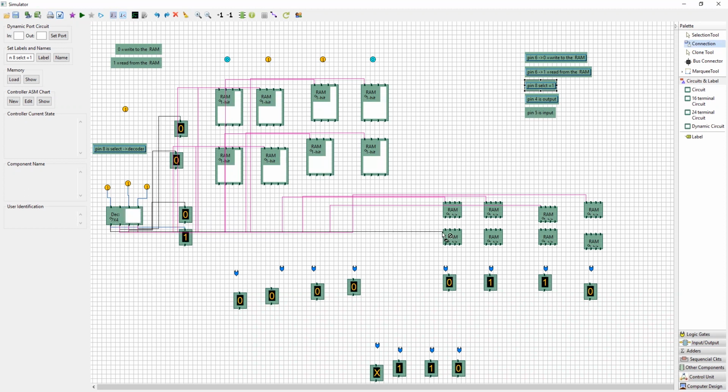So now the last decoder output goes to the last row of the RAM cells. Okay, so I hope everyone is clear on this select concept and how it works. Select is simple: all the RAM cells in a row together I want to select. For that reason, I have given the decoder output. Next I will come back to the read write operations.